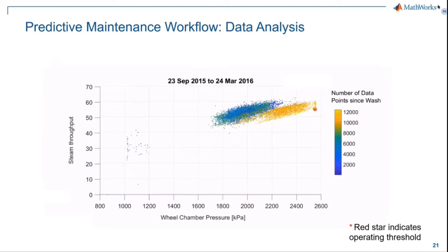From a practical point of view, the reason this happens is because as salts continue to accumulate on the blades of the turbine, more and more steam is required to maintain the same throughput. But eventually, a point is reached where the expected throughput can no longer be maintained. So that throughput gets pulled down by the pressure limit, which is limiting the steam throughput.